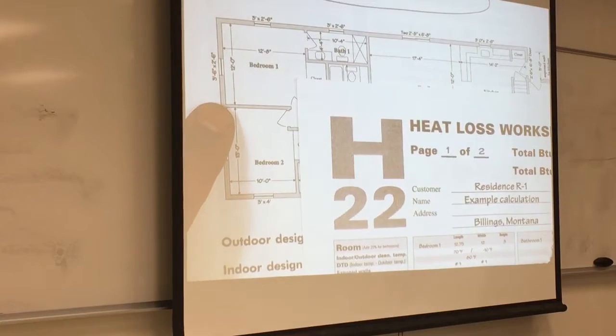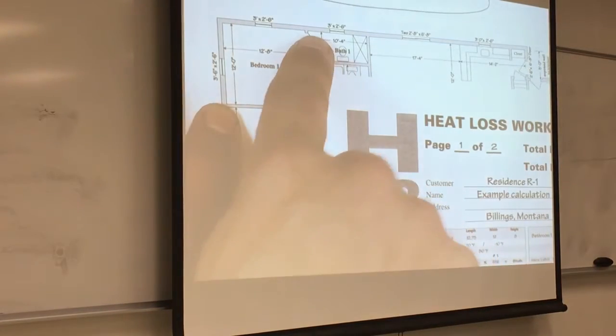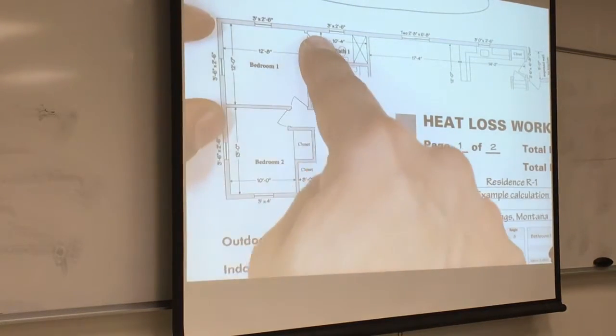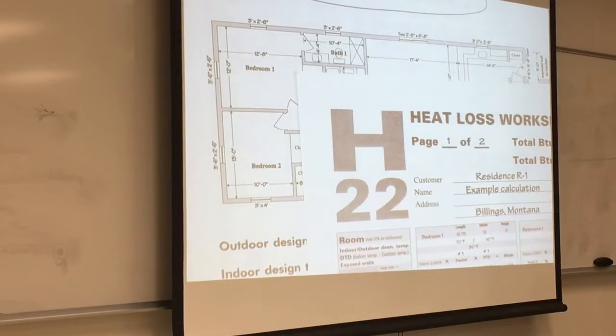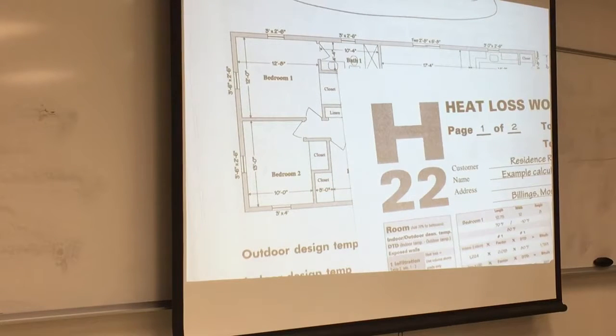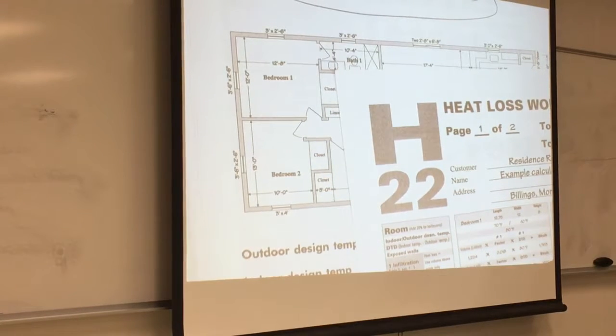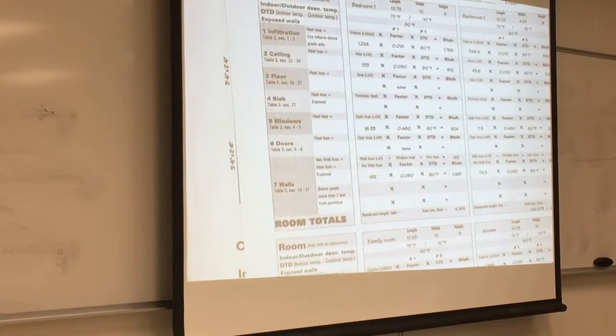Okay, we get the windows, we get the walls. The wall is going to be this area plus this area, minus the windows. Whatever you get, subtract the windows from it, and you use the factor, which is 0.08. You put the number here, then you add these together, and this is going to be your total. 12 by 8. Any questions? If you have, ask me.